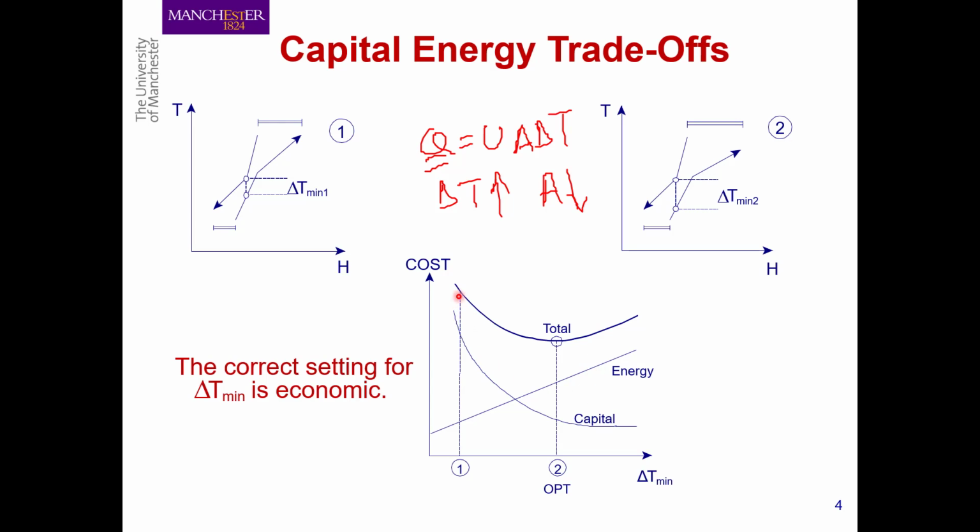Also, in terms of our total cost, we are only looking at energy cost and capital cost, but we are not looking at other maintenance cost or cleaning cost. For example, in heat exchangers, we have a lot of fouling over time. And it means that all these heat exchangers require a significant amount of cleaning cost, operating cost, and maintenance cost. So we have to consider that in the actual design of the system. So here we are just looking at a very simplified process.